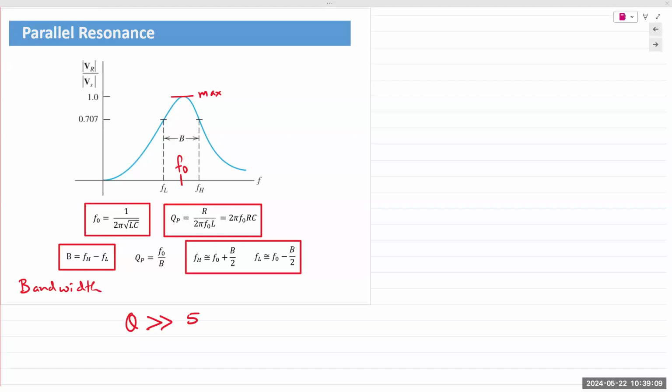So the question being asked is, what kind of electrical circuit is used to change the phase of the circuit, right? It could be a very simple circuit such as a transistor amplifier. A bipolar junction transistor is used for amplification. Just by its very nature, and again, this goes into electronics, which is a separate course, the transistor itself, when it performs the amplification, flips the phase of the output by 180 degrees. It could be a very simple circuit like that, but there are other complicated circuits also.